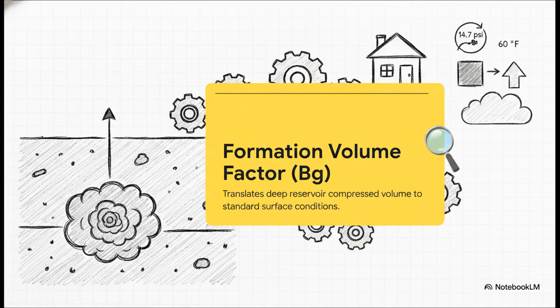It takes that highly compressed, super dense volume of gas miles underground and translates it into the actual volume it will occupy at standard surface conditions. And for the record, that's exactly 14.7 psi and 60 degrees Fahrenheit. This is the volume that actually matters when we're calculating how much gas will eventually heat your home. It's the ultimate conversion rate for energy extraction.